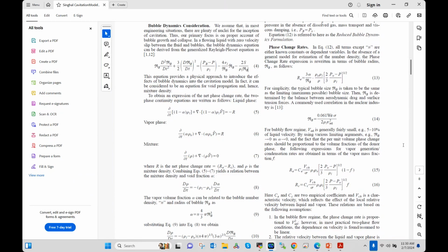So I think it depends on if you're running it with a steady state formulation or transient. For steady state, we typically converge it to 3 orders. For transient, we converge it to 1 order because you're doing it every time step. Also, please note that our convergence is relative.